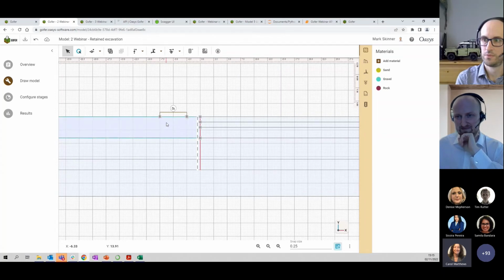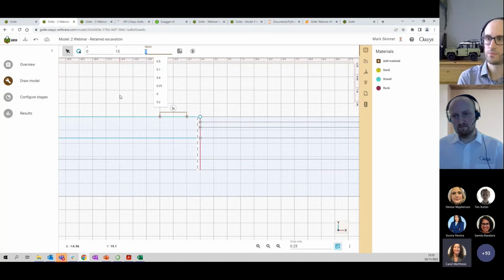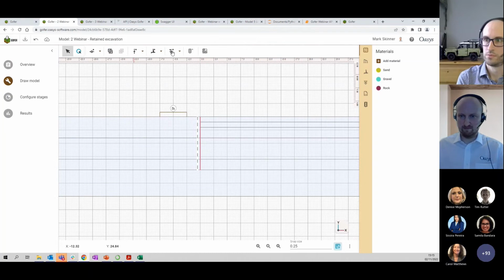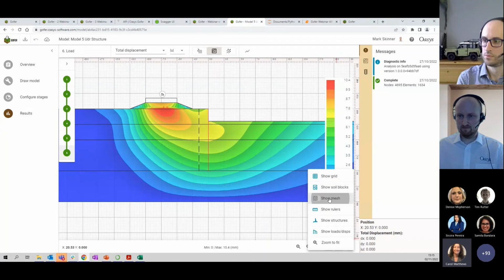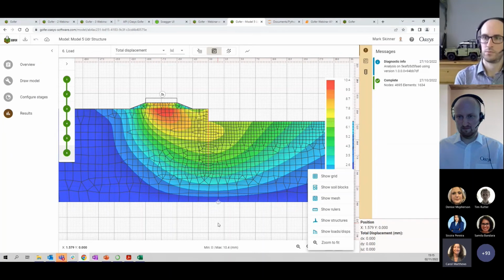So if you don't set the mesh size on nodes, it will take a general, it'll divide the minimum dimension of the model by a number, I think it's 10, and then it'll refine extra smaller elements around structures and line loads and point loads. So if you don't set the mesh sizes, the program will try to give you a reasonable mesh, but you can optionally add a neighboring element size to any node and it'll use that instead.